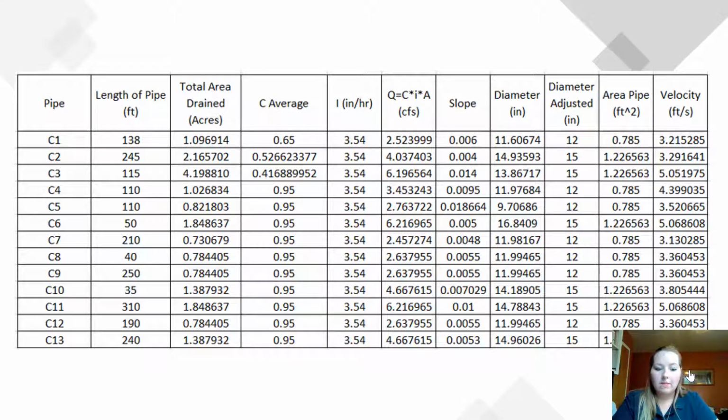I had to coordinate with pavements to make it possible to adjust the crown of the road to be on the south side of Shaw Lane. Therefore, all the runoff is directed towards drainage structures on the northern edge of the roadway, as you could see in the stormwater system figure. And with this adjustment, the subcatchments were able to be expanded to the entire section of roadway instead of down the middle where the crown would have been. And this change really did fix the issue and made the resulting velocity in each pipe within the required range.